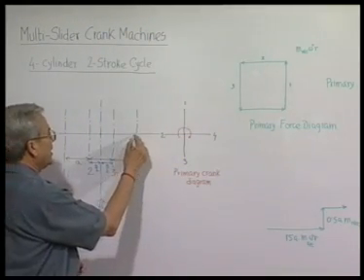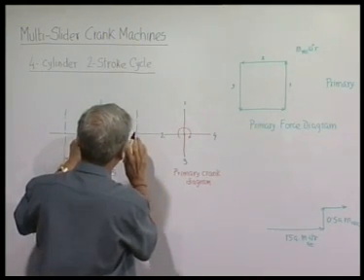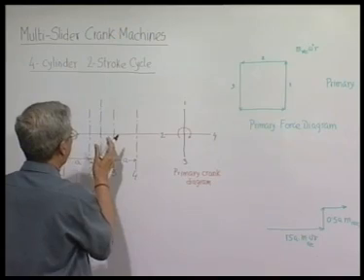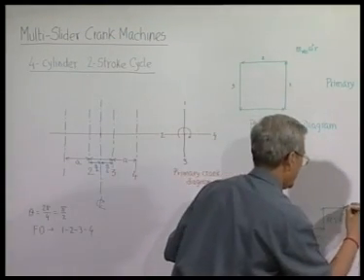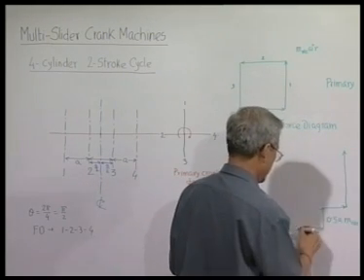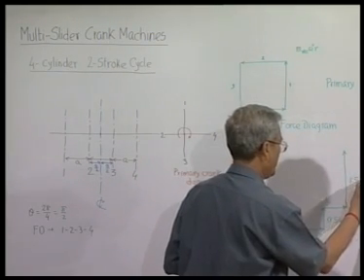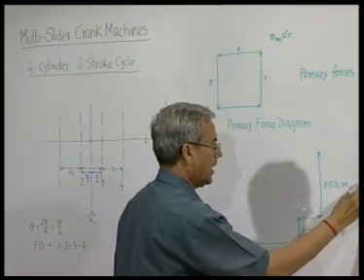And this cylinder, the force is in this direction, and obviously it will produce a moment in the upward direction. Its magnitude will be again the same as this, 1.5 a m reciprocating omega square r.